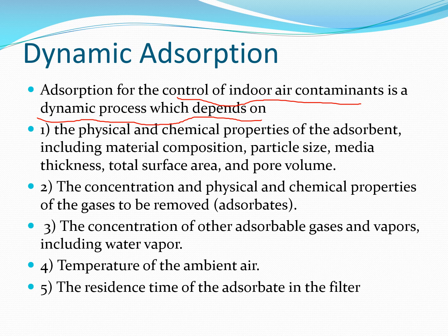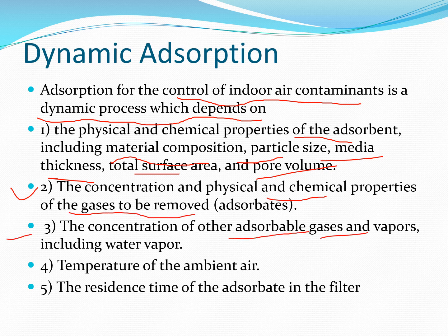So the physical and chemical properties of the adsorbent, including material composition, particle size, media thickness, total surface area, and pore volume, all play roles in the adsorption phenomena. Also the concentration and physical and chemical properties of the gases to be removed, concentration of the adsorbable gases and vapors, including water vapors, and temperature of the ambient air.